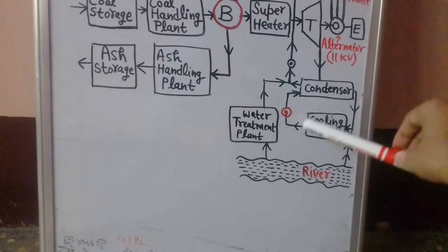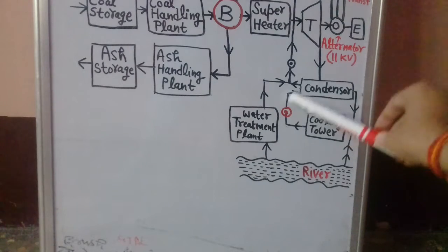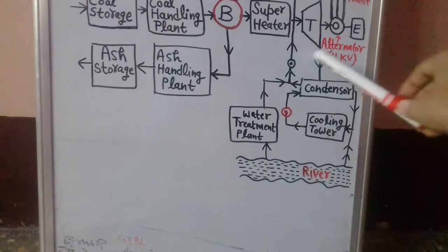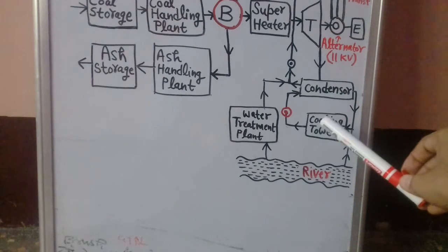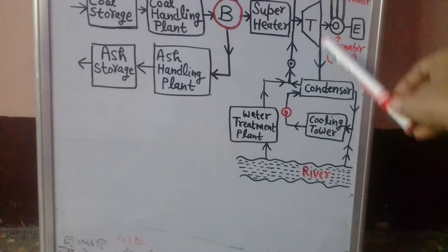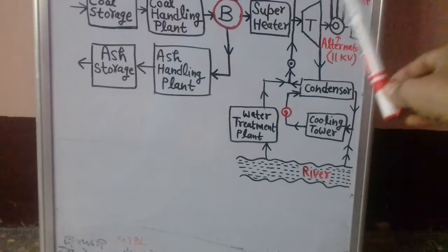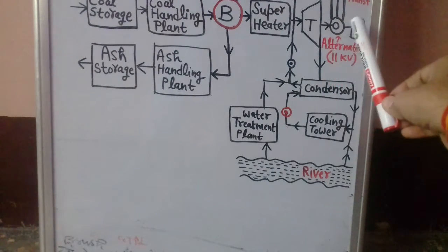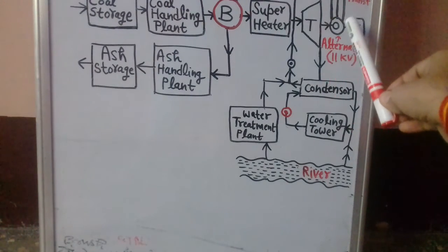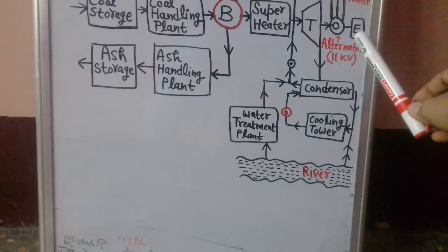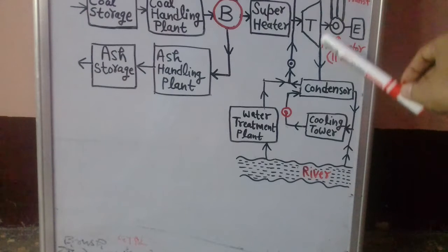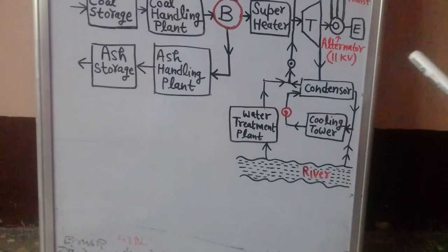So this is a feedback process. That's how we are avoiding the wastage of the steam which is coming out of the turbine. There is one steam which is being utilized for the electrical energy production, but the remaining steam that we are getting out of the turbine, we will not allow to pass on to the atmosphere directly for wastage.